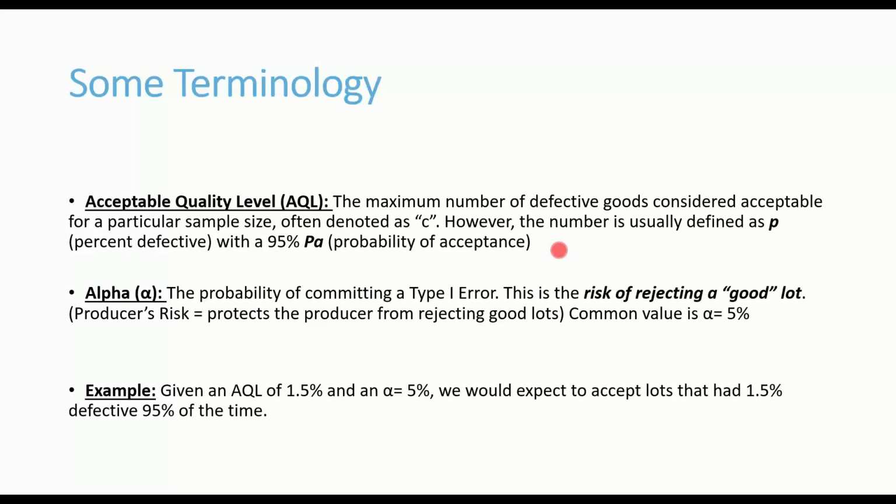However, the spec AQLs are not to be used as a way to provide permission to make defects, right? And we should strive for 100% acceptance in all of our processes. However, if there's only one defective in a sample of 100, it doesn't make sense to reject the entire lot or do 100% inspection of the items. The cost is too great to the producer and the consumer.